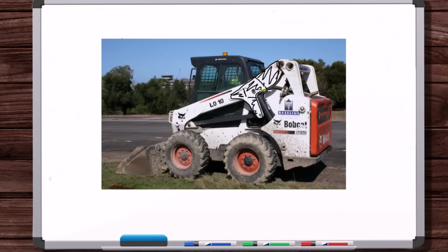Here, would that be the case? So with the different metals, would that be the case? No, it would be the same thing. It would be a stiff, rigid body. Now, if this was made of tin, like a tin can, tin is really, really soft compared to steel. Well, in that case, if you're applying loads typical of what steel would handle, then all of a sudden this would really bend like a tin can, and that's not a rigid body anymore.